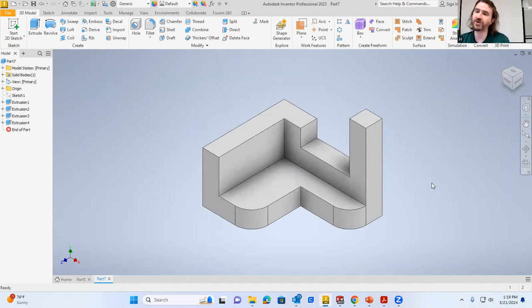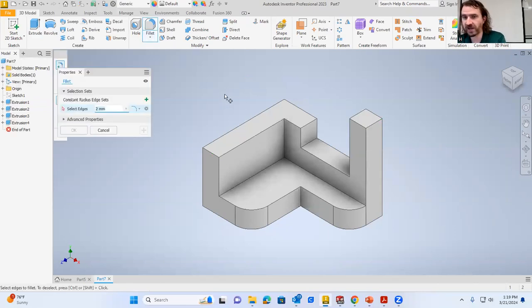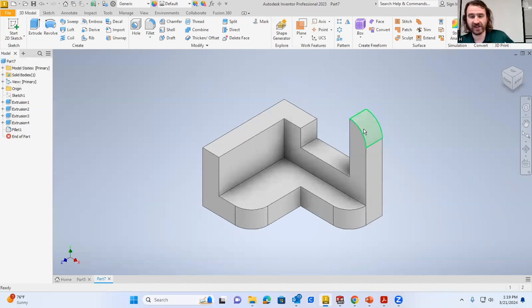There are two features though that needed to be added because we couldn't do those in the preliminary sketching that we did at the top view. We need to chamfer this wall here from this edge. We need to chamfer this edge here. We need to fillet this edge here. So let's fillet. So fillet radius of 10. Again, the fillet tool here is the one I'm using in the 3D model tab because I'm filleting 3D material. Makes sense, right? Obvious. So hit enter, that fillet is done.